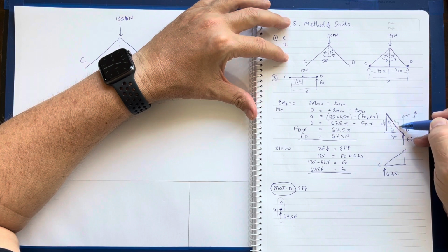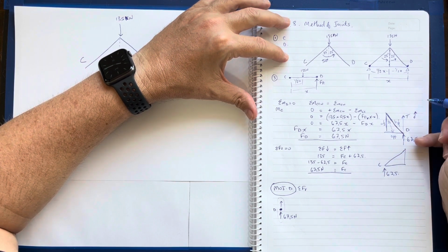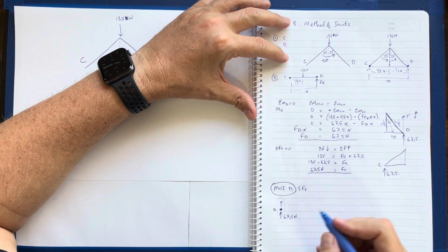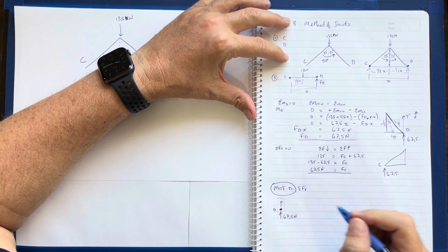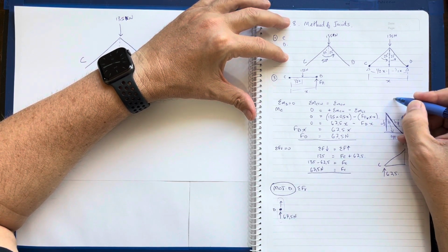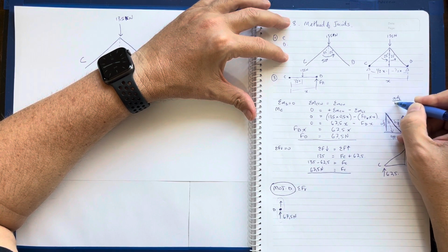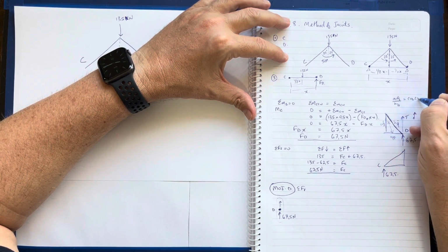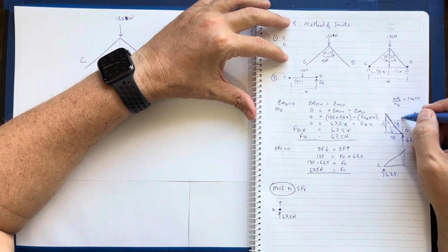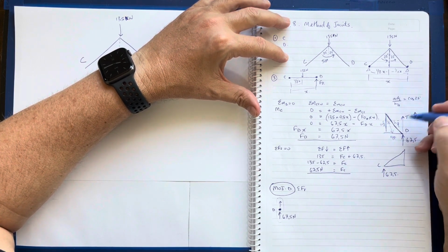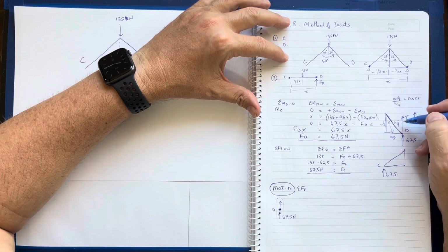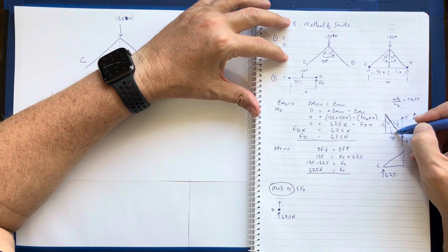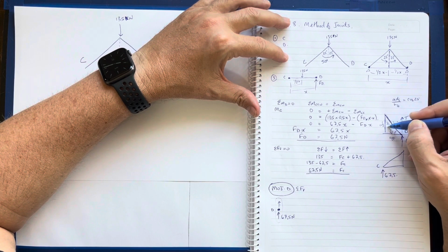So D would be the hypotenuse, and the vertical force would be the adjacent. Adjacent over hypotenuse is cos, so effectively this force, adjacent over hyp, equals cos 25. I know this is normally counterintuitive. Normally what we do is if it's vertical, we say it's sine, but that's if the angle is here. Now the angle is here.